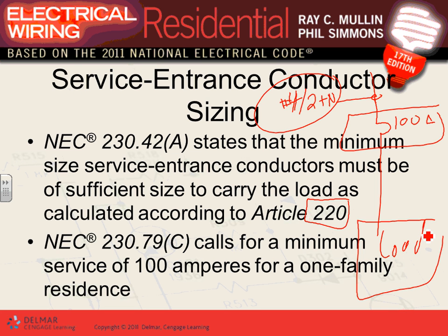How did I come up with 100 amp? You guys are the service entrance. The load calculation that I gave you, that sheet that I walked you through the other day. You size the service disconnect based on the load inside your building. And then you size the service entrance conductor based on the service disconnect. Can you guys see how everything depends on each other? So first, you know what the load is. From the load, you size your service entrance disconnect means, the circuit breaker. And from the circuit breaker, you size your service entrance conductor. So important. You guys are going to do this 3 times with me: commercial, industrial, and residential project.